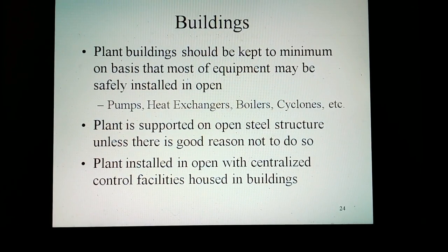Buildings. Plant buildings should be kept to a minimum on the basis that most of the equipment, including pumps, heat exchangers, boilers, cyclones, etc., may be safely installed in the open. The philosophy should be that the plant is supported on an open steel structure unless there is good reason not to do so. Thus it is to be installed in the open with centralized control facilities housed in buildings.